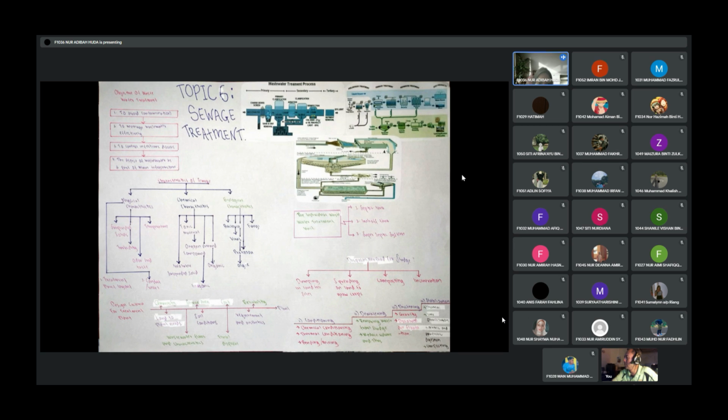Design criteria for a treatment plant: water quality, land requirement for the plant, wastewater flow and characteristics, service area, soil condition, final disposal, reliability requirement, and aesthetics of the plant. So the individual wastewater treatment units are the septic tank, Imhoff tank, and sullage septic system.